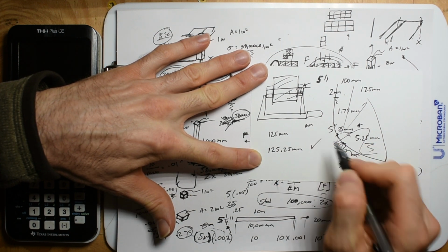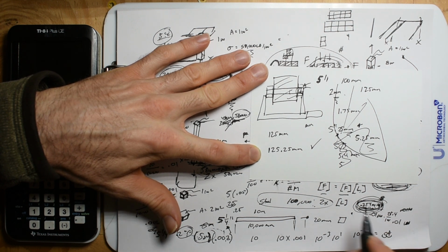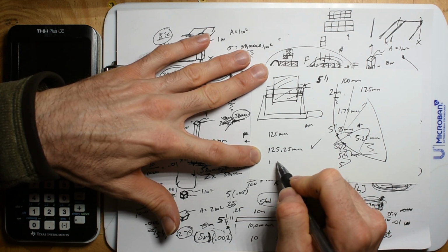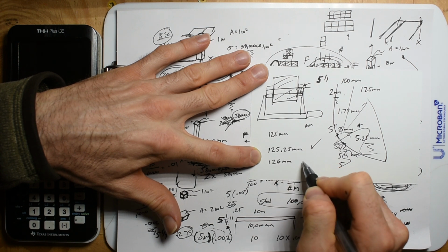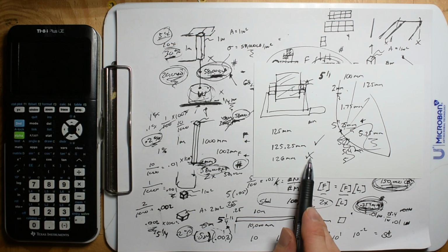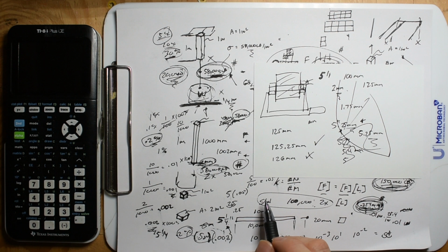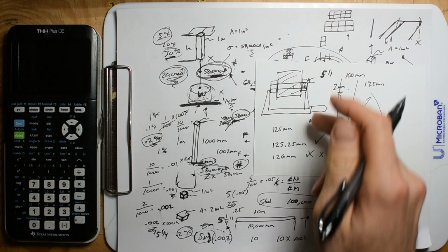I have done a very good job of perfectly tightening it up to its elastic limit. So if I go measure and it's 126 millimeters, I have permanently plastically stretched the bolt, you know what I mean? So let's just call that no bueno. No big deal for this bolt.